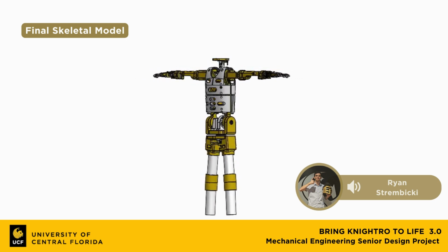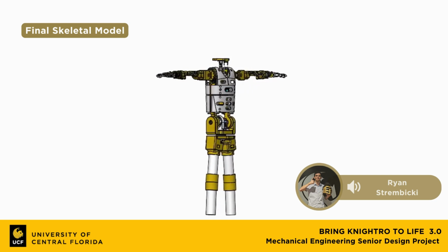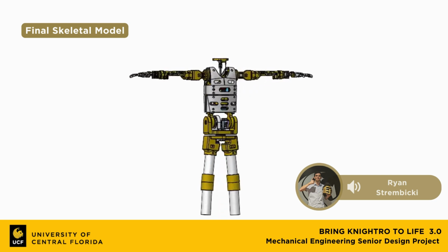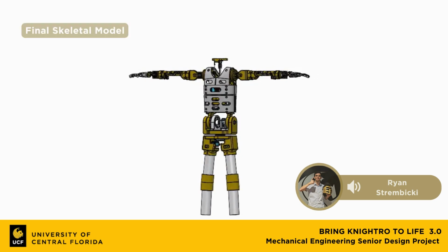In a similar manner, the torso rotation function is created through a 2-to-1 gear ratio to provide smooth and controllable movement of our figure. Finally, these components were modeled specifically to be 3D printed and assembled easily using brass thread inserts and a variety of fasteners.